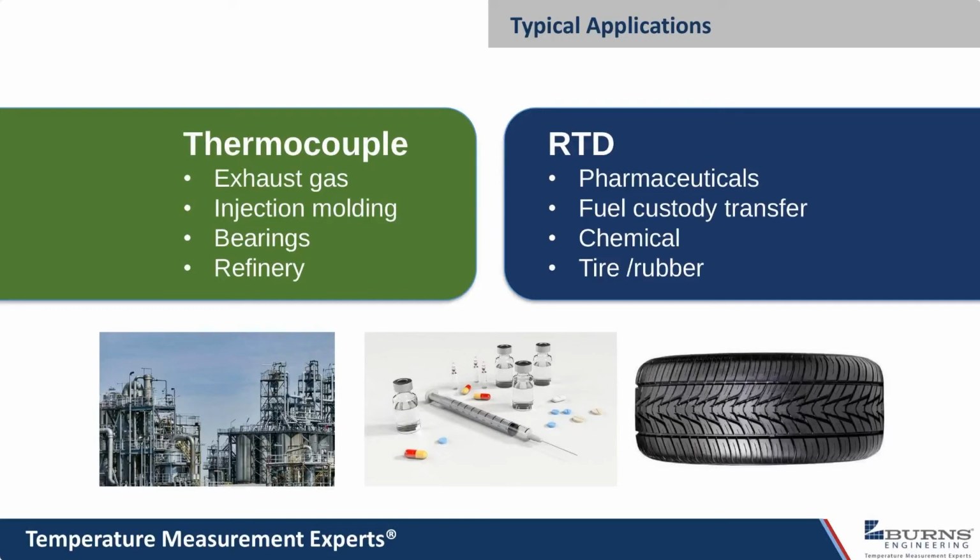Of course, that fuel expands when it warms up. And you need to know the temperature of that fuel as it's going into the truck so that you don't overfill it and have an overflow situation. So that sensor has to respond very quickly and it has to be very accurate, so they can use that temperature in the volume calculation. If the truck holds 10,000 gallons at 60 degrees in the underground tank, but it's 100 degrees where they're delivering, it's going to expand quite a bit.